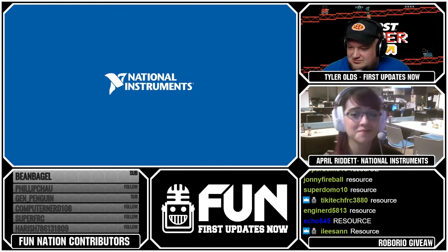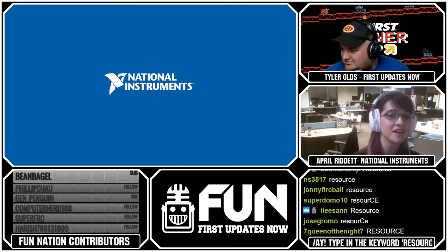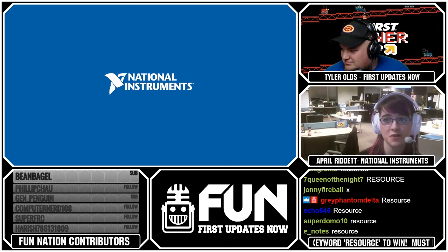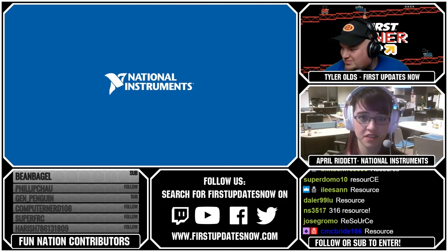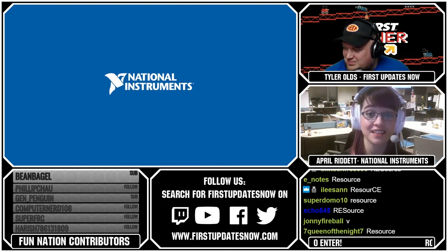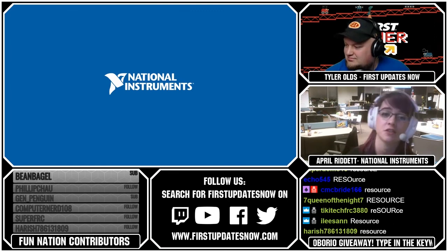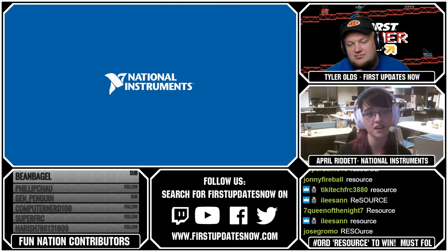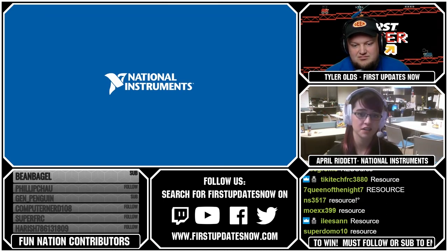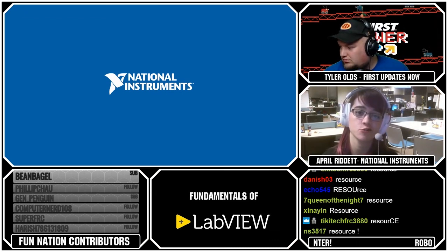It's a good question. They're typically less unrelated than you think they are. When you edit something in LabVIEW, it gets that asterisk, the same as you see in Microsoft Word or anything like that. So if you edit anything that touches those VIs, so any controls, any other programs that might use those subVIs, it's going to ask you to save them. That's typically where we see that come from in terms of source code control.